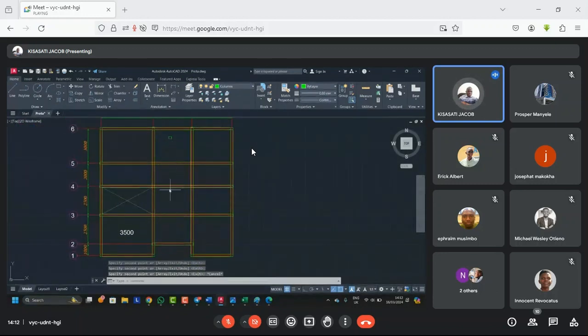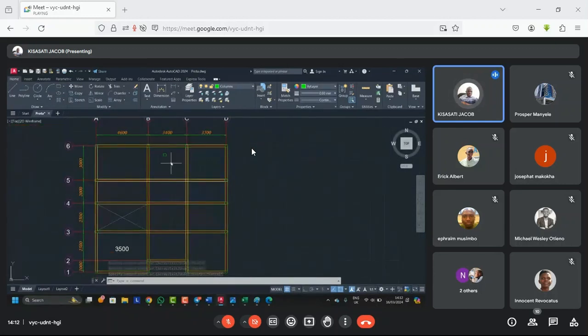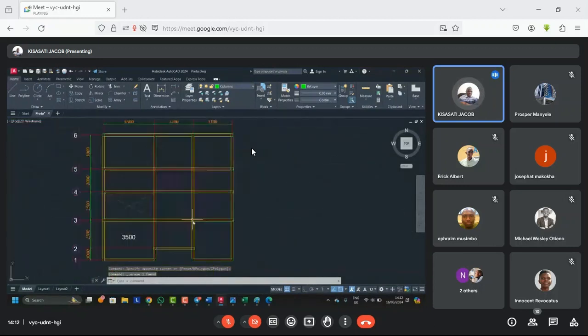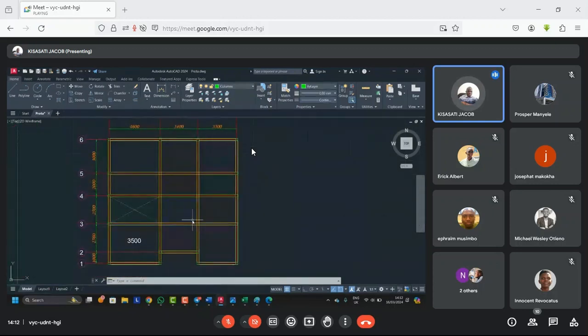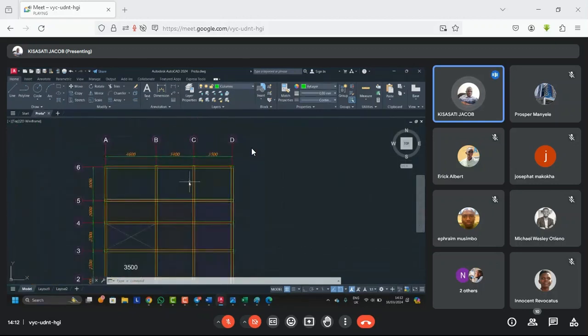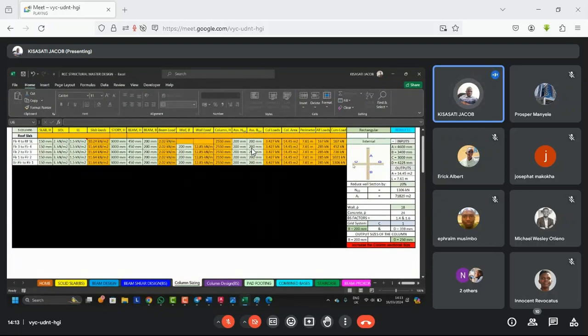What about the internal beams? For the internal columns, we can use this one. Yeah, let's use this one. So for this internal beam, the dimensions we have are 34 and 35. The beams following each other are 34 and 35. So first of all, you come here, then select internal, like that. So CD is 3400 and 3500, like that.